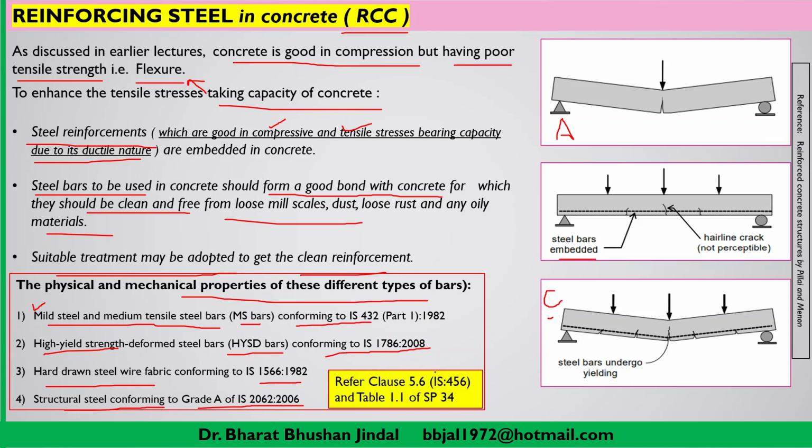For more detail, you can refer to clause number 5.6 of IS 456, and you can refer to special publication SP 34, where table 1.1 gives all the related and important information regarding the steel bars which you can use as a reinforcing material in RCC structures.